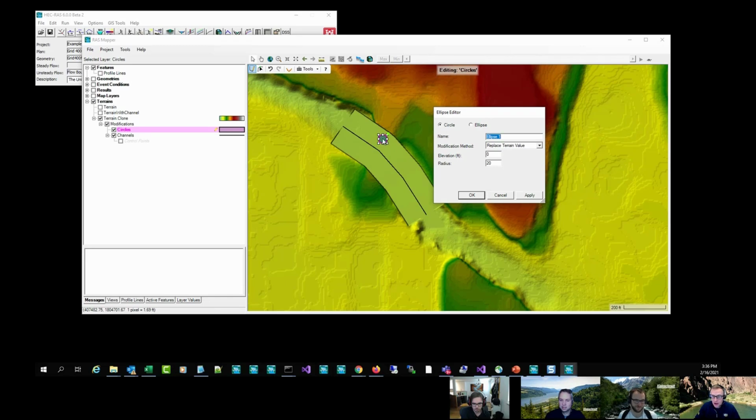It's going to automatically add it. You can choose. You can make it elliptical. If you make it elliptical, it'll give you a minor axis as well. It's actually the radius too, so it's even bigger. Oh yeah, it is the radius. So it's a Mondo one, but everyone can see it on screen, I hope. And then you put in your elevation. So I think 945 might work. I'm not exactly sure. That's how high you're going to lift that terrain out to 945.